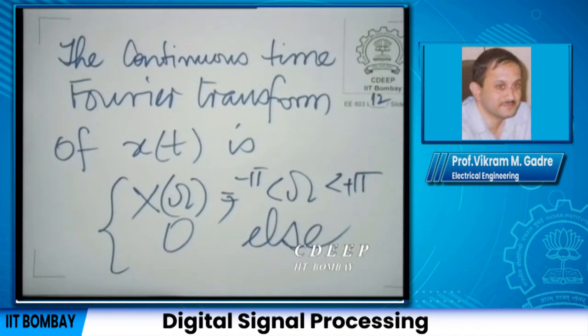In fact, here I introduce this idea of the underlying continuous time signal in general. Whenever you have a discrete time Fourier transform, restrict it to the interval minus pi to pi and cut off all the rest, make it all 0. What do you get? You get the original band limited signal, which was then sampled at the integer points to give you the samples xn.